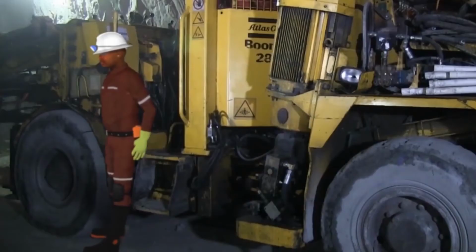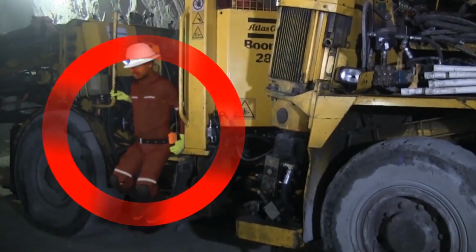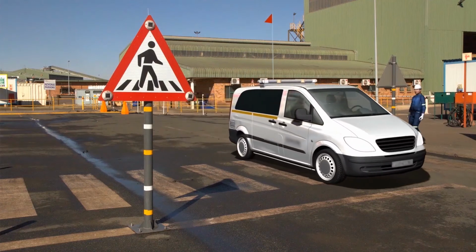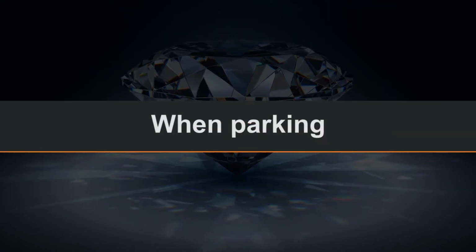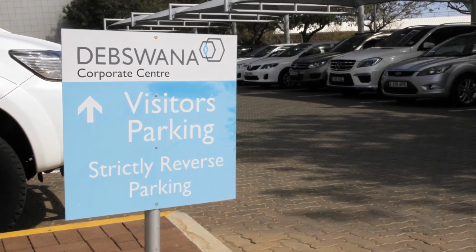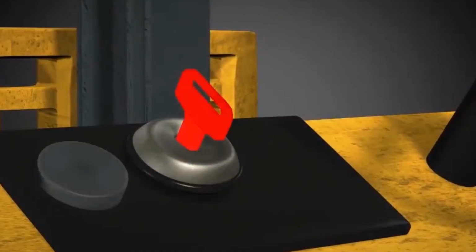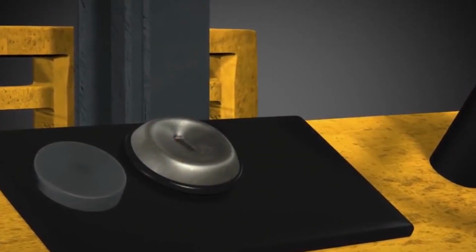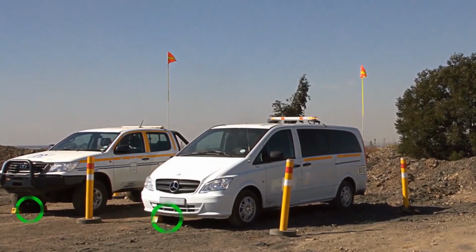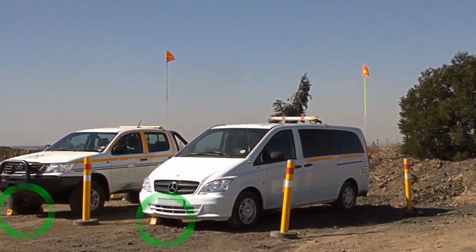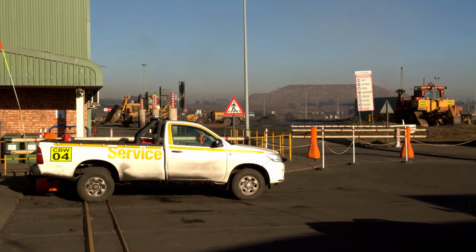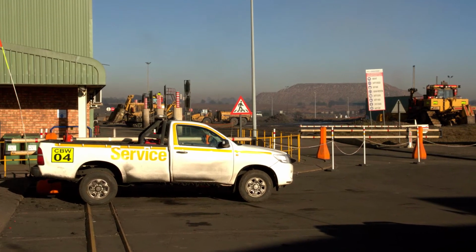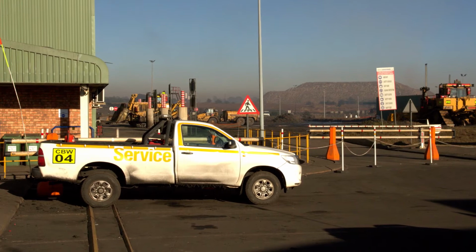Always acknowledge pedestrians and stop when they can't move out of the way. Bring the vehicle to a complete standstill before allowing passengers to get in or out. When parking, reverse park where required. Switch off the engine and remove the key when you get out. Always use chocks or trenches to prevent your vehicle from rolling away. Park in designated areas, separate from heavy mobile equipment.